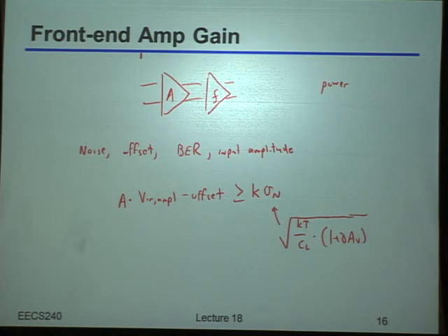I'm obviously giving you a simplified thing here, but let me be absolutely clear, why is it that I may have wanted to point out what that sigma n actually is here? Say that again? Yeah, exactly. The noise actually has the gain in it, right? So you have to be careful when you do this calculation or check, because the gain doesn't just appear on one side, it actually appears on both sides. So obviously, whatever you do, you have to be self-consistent, so to speak. Make sense to everybody?